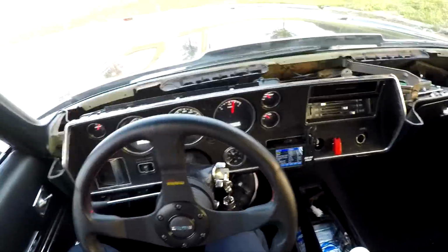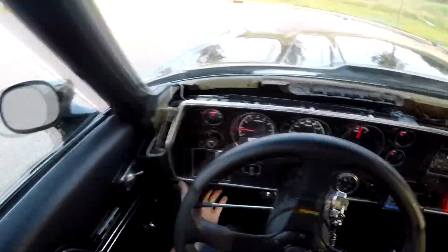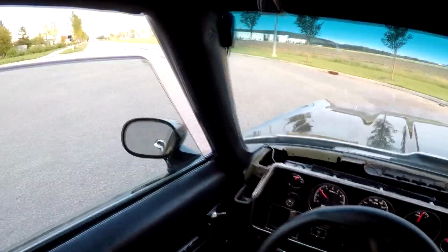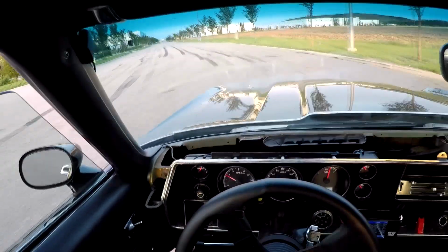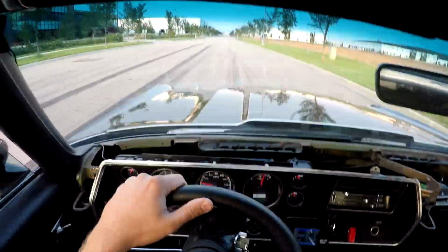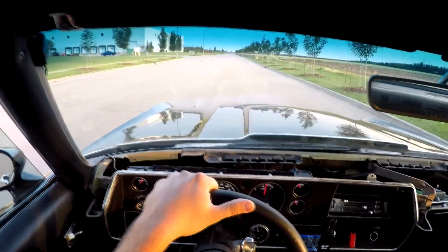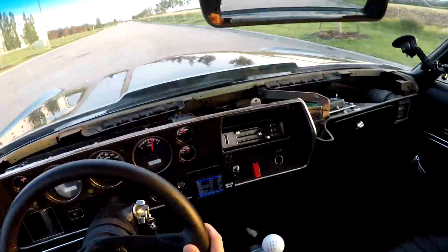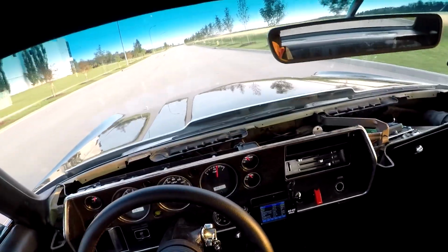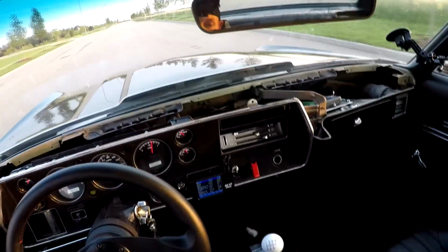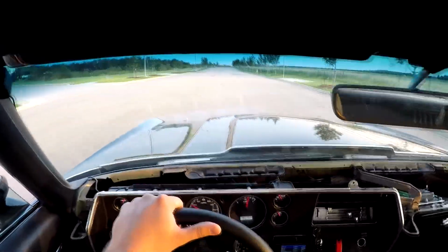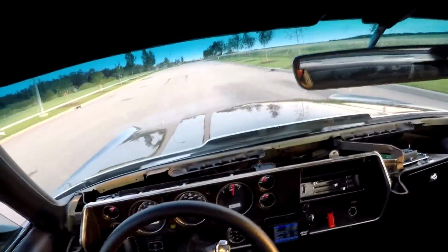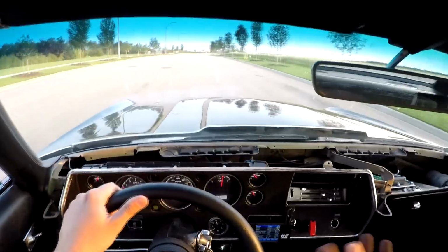So simple as that. Go for a drive and get some miles on it. I like to find some areas that are nice and secluded so you're not interfering with people. Of course you want your fluid temperatures to be up to operating temperature to get the most accurate results. You want to try different throttle positions, different RPMs, different loads, just to get as much information as possible so you can break it down later on.